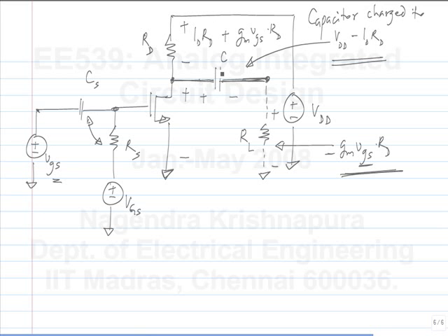So this particular amplifier works only if the frequency of the increment VGS is above a certain value. If that's the case, at those frequencies we assume CS to be a short, and this maybe CL also to be a short. So this circuit is more complicated than before. So we will analyze this using the small signal incremental picture. The incremental picture simply gives you the increment in various parts of the circuit depending on the input increment, right.